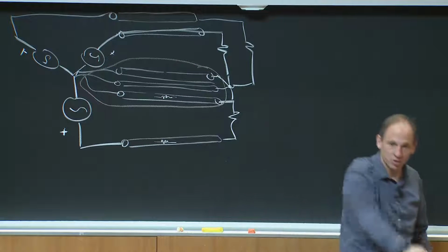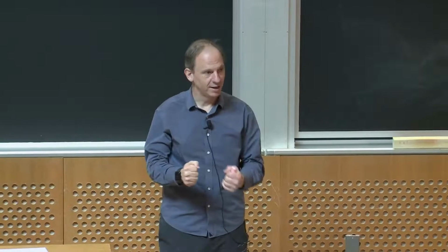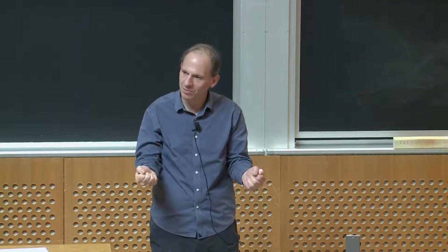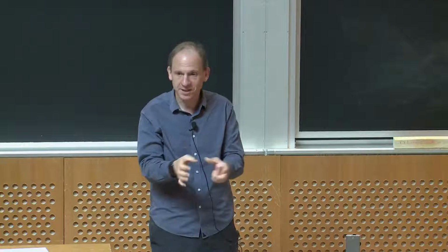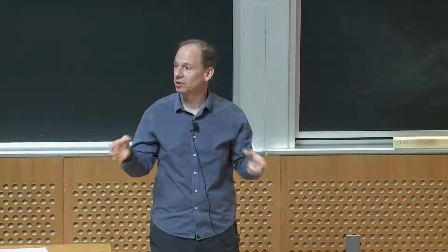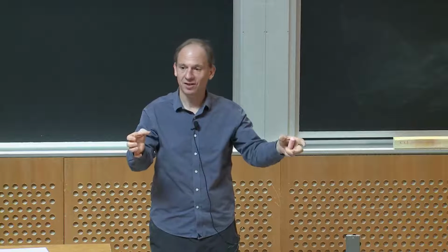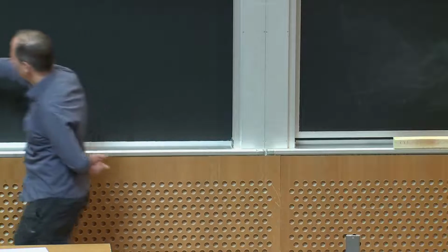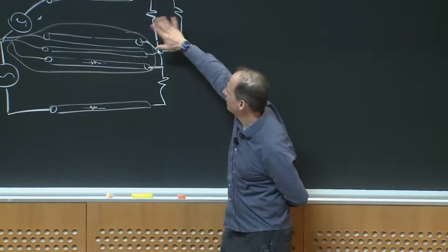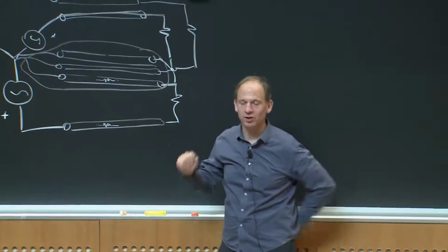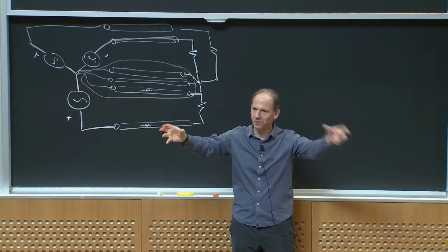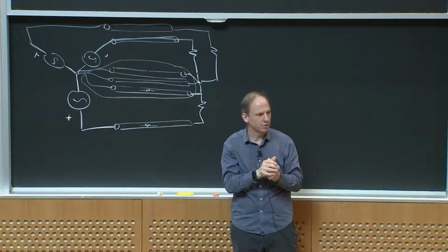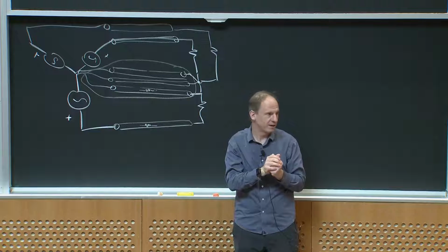That advantage also applies to things like motors, right? So if you wind your motor, you can get away with effectively less copper to do the same thing. It also applies to fluxes and transformers, right? We showed, if you're going to have 3-phase carrying a flux, essentially what we're doing here is using the other phases to be our return conductors, in the same way you can use your other legs in a 3-phase transformer to be your flux returns. Okay? So there's tremendous advantage in reducing the size of equipment by using polyphase.